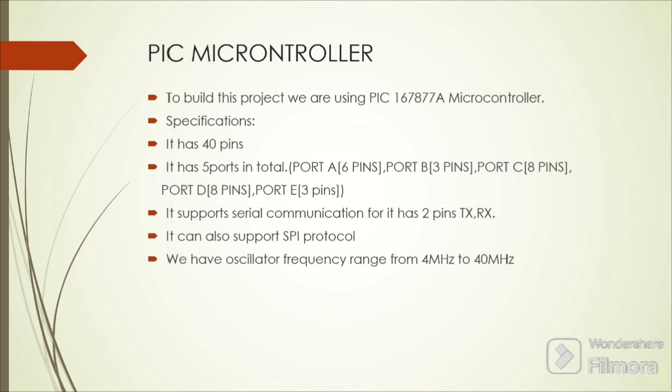And also it supports serial communication. It has a transmitter pin and a receiver pin. It can also support the SPI protocol, serial peripheral interface, and its clock frequency ranges between 4 MHz to 40 MHz. So this is all about the PIC microcontroller.